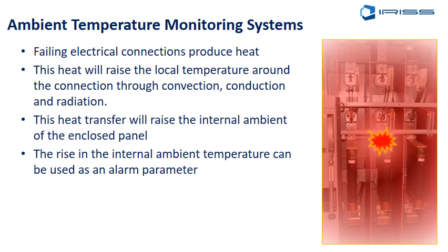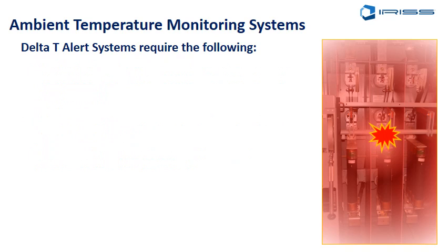But very simple, it doesn't matter how many connections there are, just one connection can raise the temperature of a panel relatively quickly. Although they're smaller rises in temperature, we can set the alarm parameters quite tight to pick up these small ambient rises.